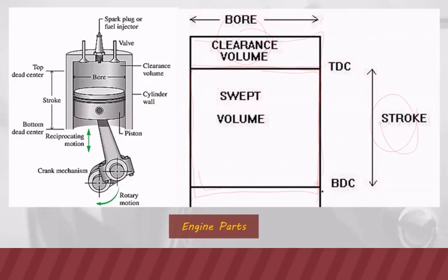The stroke from the bottom dead center to the top dead center will not reach this point here, to give clearance, and that is the clearance volume. So this one here is the stroke, and then the diameter of the cylinder is the bore.